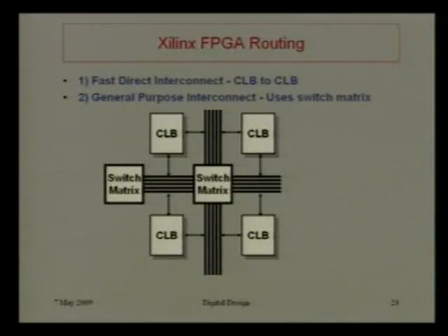So here you will see that actually FPGA is nothing but a lookup table, LUT, and a lookup table is nothing but a memory. Think that my behavior is like a table: if this is the input, this is my output. So whatever the expression, Boolean expression, everything I can always represent like this, and FPGA has done that. Everything is written there, and now depending on your requirement, it is just switching. This is the idea. I am not telling much more.